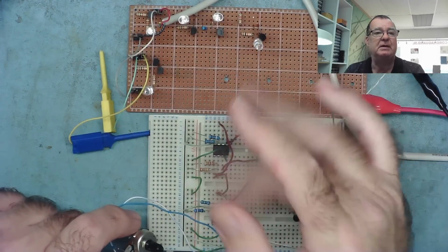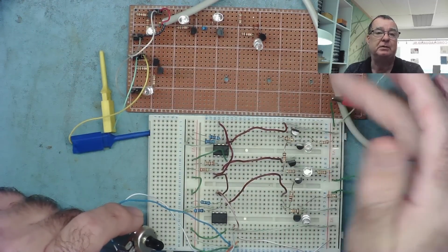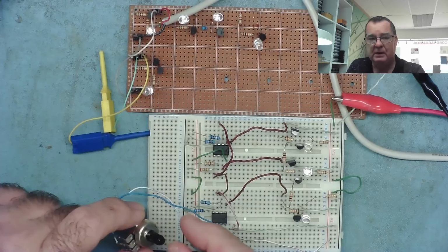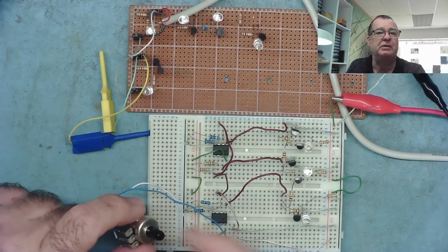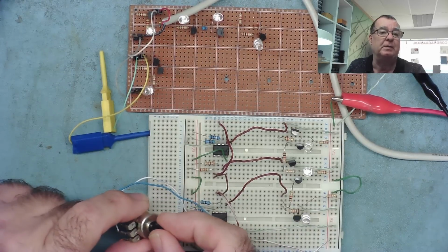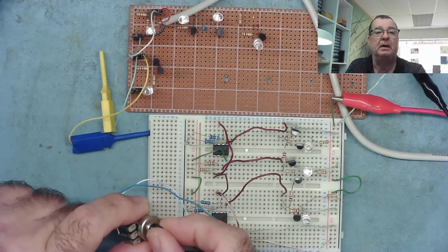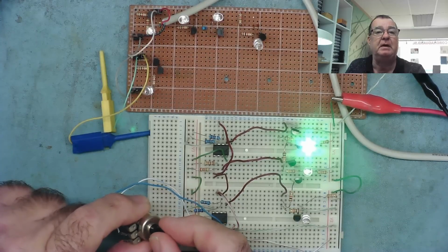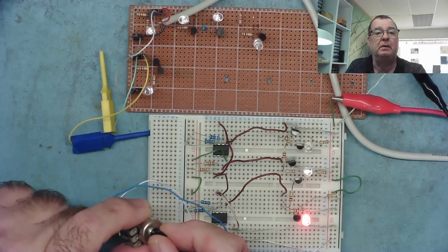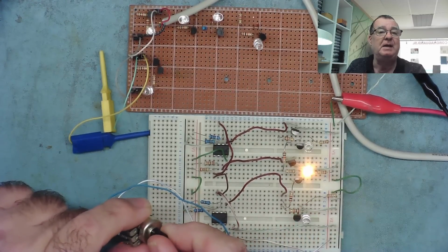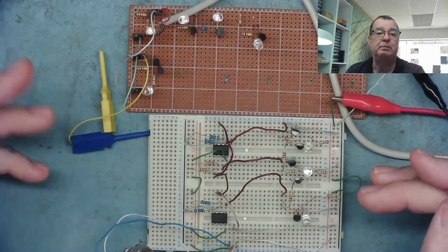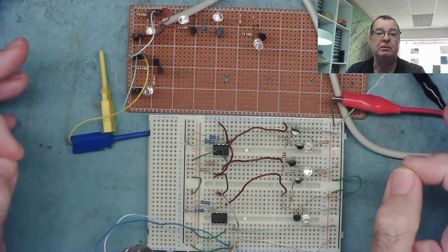So this is made with 2 comparators and 5 transistors, effectively wired as a logic circuit, and this one basically lights the LEDs in sequence depending on the voltage of the input. I'm going to set the voltage by just adjusting this potentiometer, and you can see they're all off until a certain point I get the green LED, more voltage I get the yellow LED, and then a little bit more and I get the red LED. So we can have a look how this sort of circuit works. Again, we can play around with it, introduce problems, and then see how we can diagnose them.